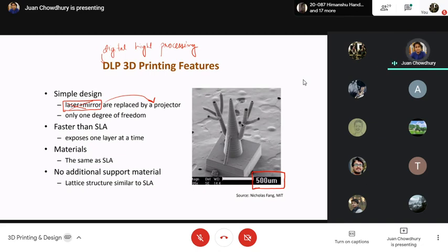Here, instead of a screen, we are beaming images on a layer of substrate, or a resin, whatever you would like to call it, which implies that this particular layer in the structure will be fabricated in one go, because we are not making a laser move from point to point. What we are doing is exposing the surface of the resin to a single beam of light. That is the advantage.